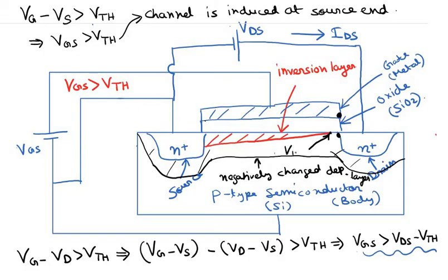So this point has the voltage VDS sat, and the extra voltage, that is VDS minus VDS sat, provided that VDS has become higher than VDS sat, this extra voltage basically drops across this very small depletion region where the channel has ceased to exist, or this very thin depletion region which is exposed, or where there is no channel. Okay, so basically this part.